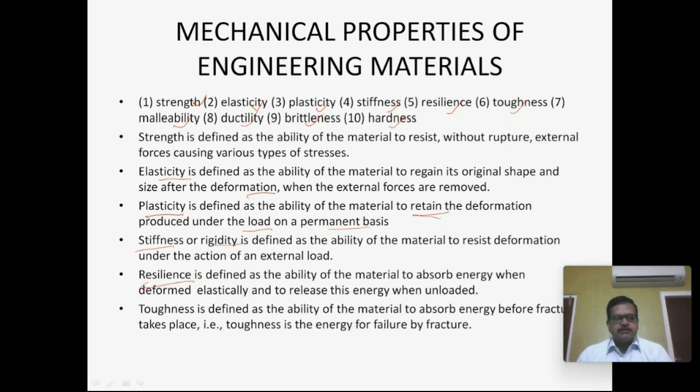Next, resilience. Resilience is the ability of the material to absorb energy when deformed elastically and to release this energy when unloaded. This is very important. So resilience is the amount of energy absorbed by the material within the elastic limit.